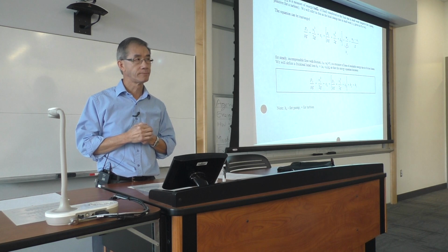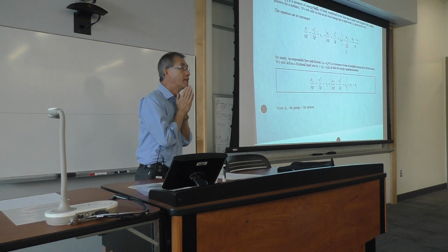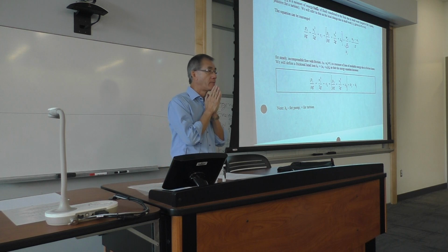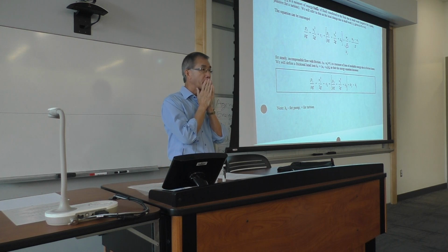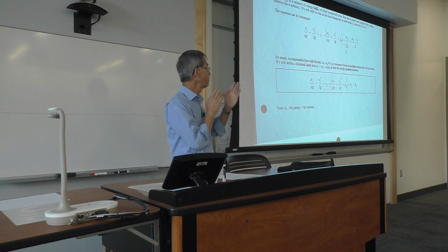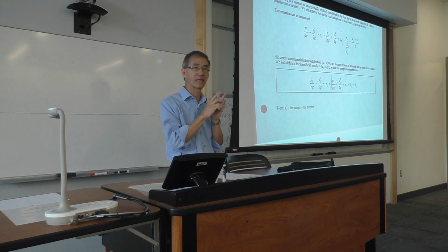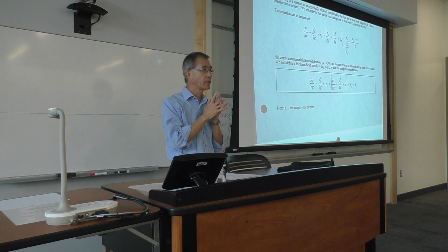Yes? For fluid flows, could anything other than friction cause a change in internal energy that would contribute to the head loss? Not unless you start adding heat transfer. Okay. The answer is no. The only thing that happened here is friction. The best case scenario for you is you neglect friction. All right? Then by chance it becomes Bernoulli. But I don't want to use that term.